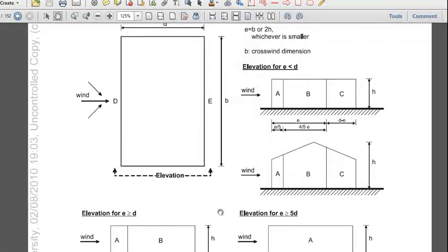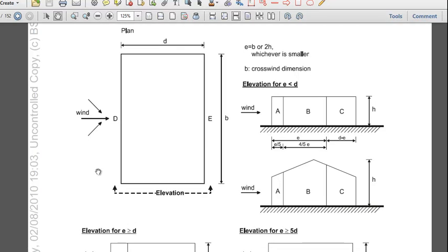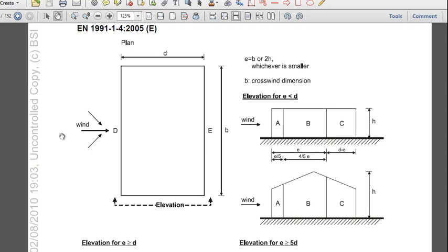Now, before I take you to this section, we need to look at figure 7.5. You will apply or calculate the wind loads in orthogonal and non-orthogonal directions, but you can reduce the critical directions in which you will evaluate the wind loads to the orthogonal directions. Okay? So you calculate the wind load at 0 degrees, 90, 180, and then 270.